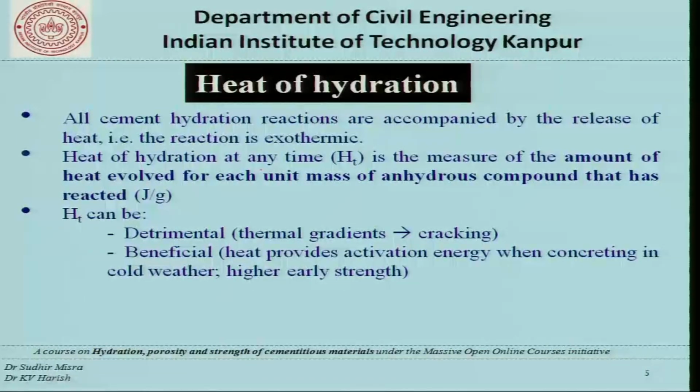All cement hydration reactions are accompanied by release of heat and the reactions are exothermic. Now, the heat of hydration at any time, since this process goes on for several hours, several days, at any time which is given as HT in this slide, is a measure of the amount of heat evolved for each unit mass of anhydrous compound that has reacted.